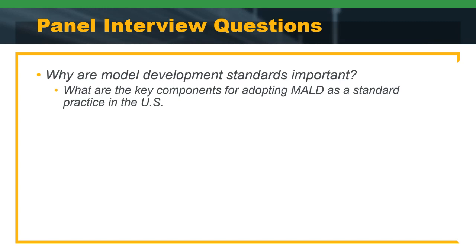And once you start to organize information, then you run into this conundrum of, how do I organize this information? And in the buildings world, they have classification standards. Construction specifications generally were organized according to Omniclass and Uniformat classification system standards, and they were very object-based. So it was pretty easy to take that standard and apply it to a BIM model where you were inserting a toilet object, and you had a toilet object classification, and you had a toilet object in your specifications, and it was a one-to-one correspondence between the three. And it's a little more challenging in terms of our infrastructure assets, and so that's something that we still need to work out as an industry.